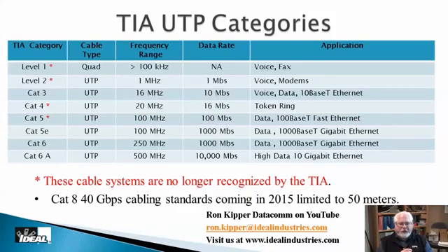And so Cat 6, will it support 10 gig applications? And the answer to that is it could. Now, will it support it to 100 meters in length? I should say, the answer is we don't know. Probably not. You'd have to test.